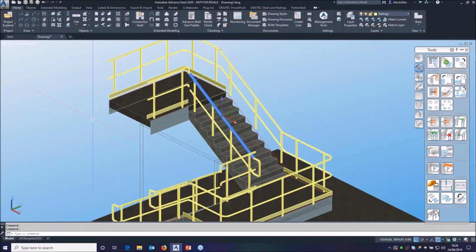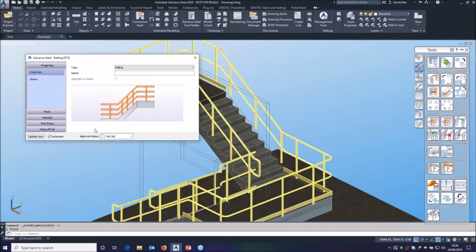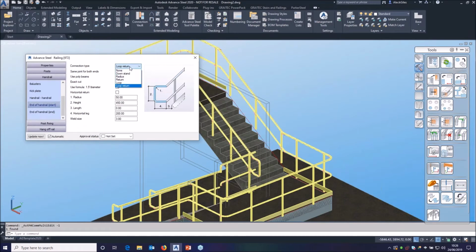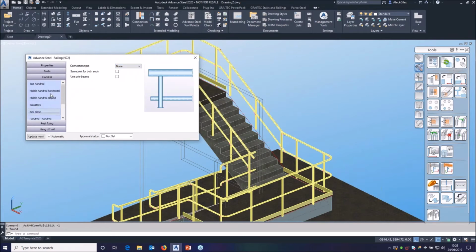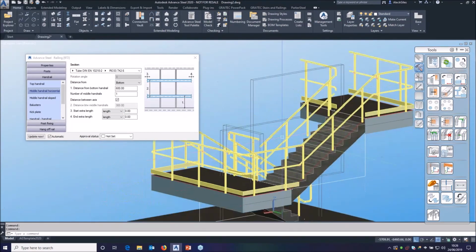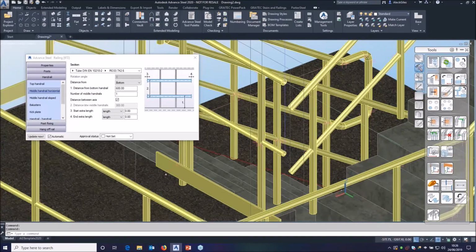So going into this second flight, I shall turn off the loop, make sure I've got some middle rail, and once again, if you look at how that's connecting, we've got to make sure that these are going to link up somehow. So this needs to turn around the corner a bit horizontally and then join up with this coming down the slopes. That's going to be over here somewhere, so I need to move that post up at least one tread.